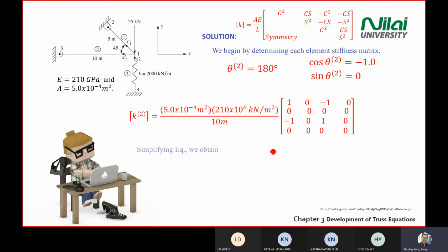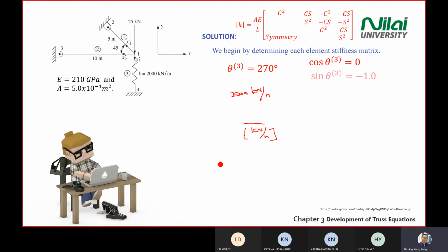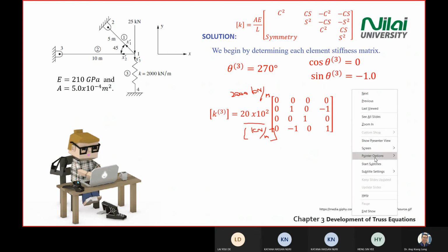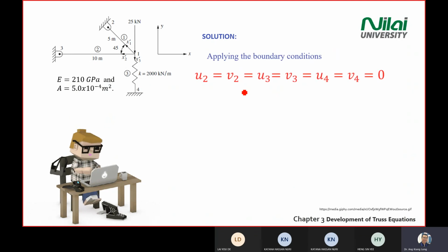Okay. So now we want to combine. All right. Combine all these three together. So we have three matrices there. Yeah, before we combine, we will have the boundary condition again. So from this case, point 2 was mounted to the wall with a pin. Point 3 was mounted to the wall with a pin. Point number 4 is straight away inside the floor or the wall.